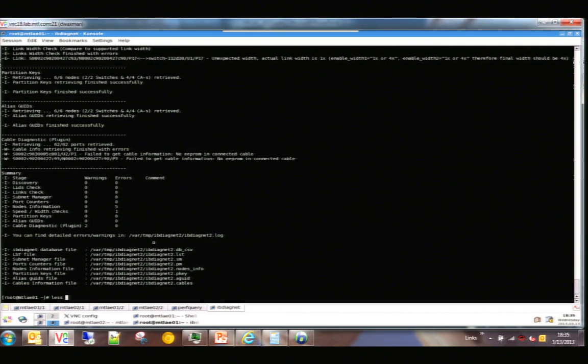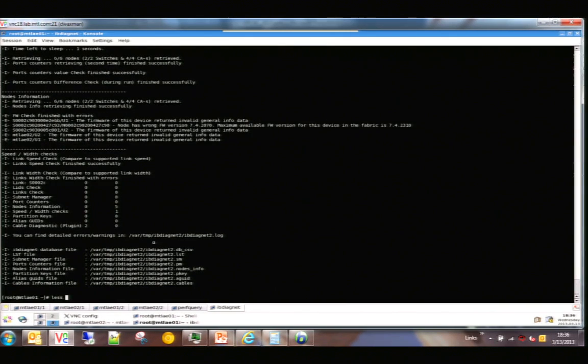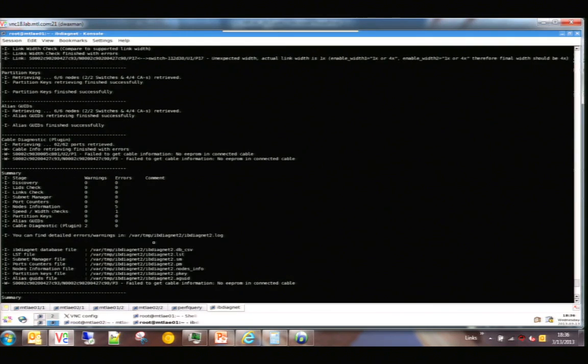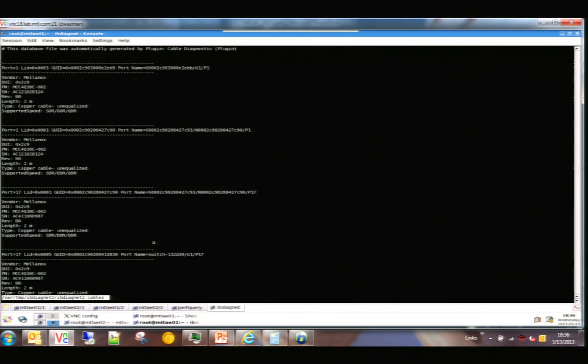This helped in the previous presentation talking about the cluster bring up. We had seen a lot of cable issues that were discovered and caused performance issues on a cluster. So basically, Mellanox engineers used this tool to trace down the cables and check whether they are from the same batch. Eventually, it was discovered that a bad batch of cable, a bad wafer, caused the cable chips to be erroneous, making the cables improper to use.